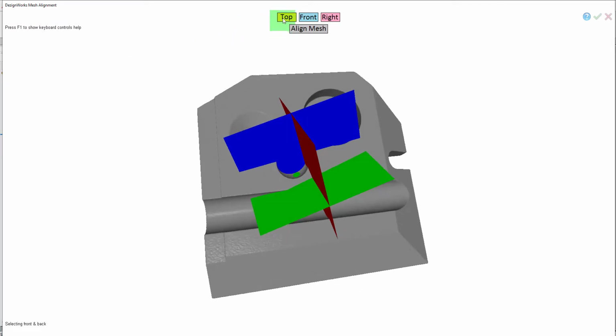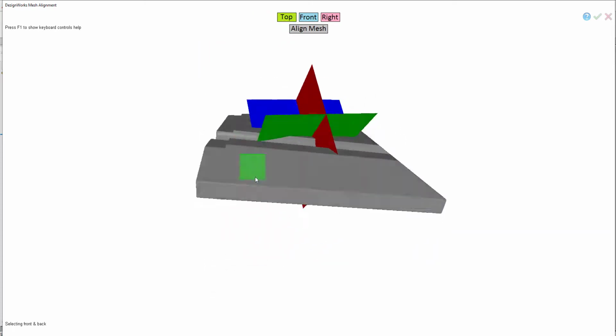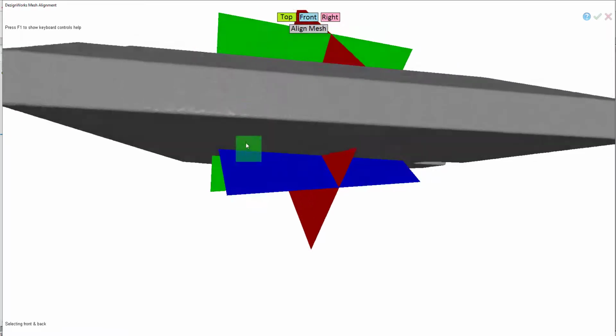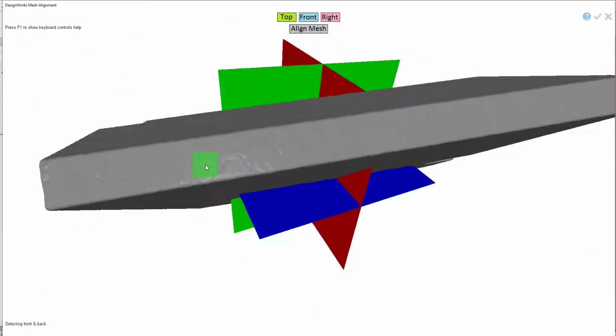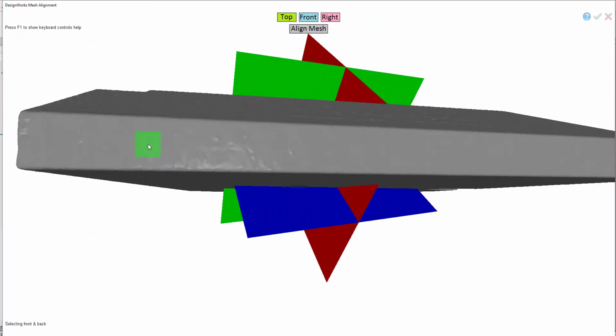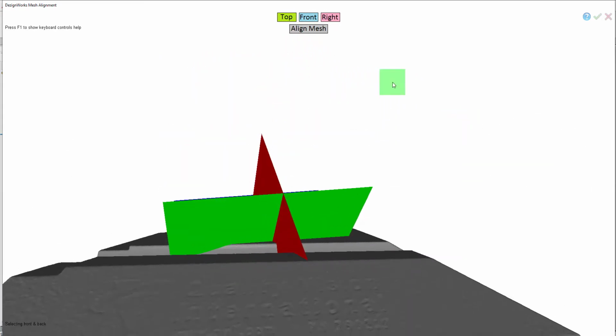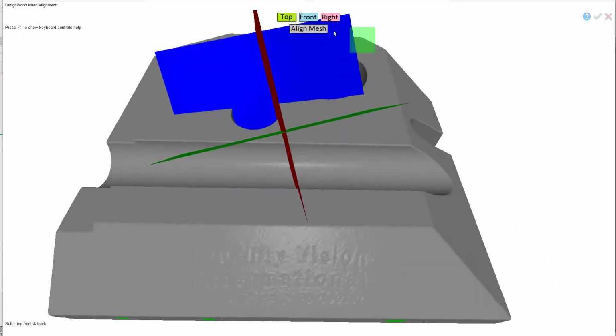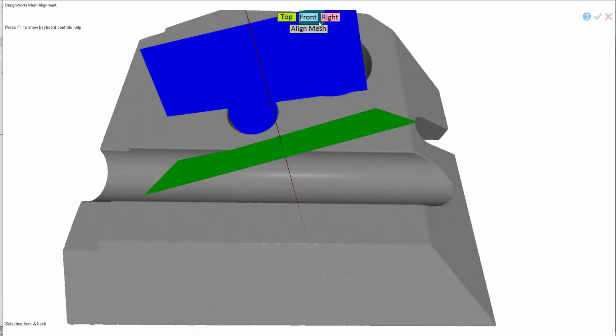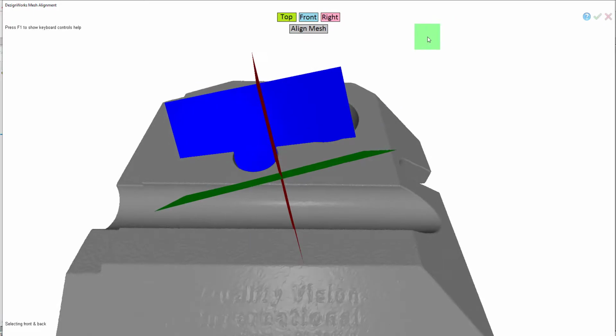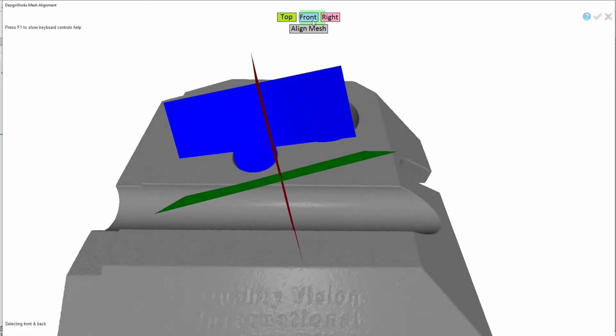Now that's in green, it correlates to the SolidWorks top, which would be across the front. So we're going to zoom in with the mouse, or if you have a 3D connection device, you can simply tap with the left mouse button and tell it this is the front. Come back up here. Make sure your part's not sitting over the icons, or you'll actually select on the part. So notice I moved the part from the icons. I'm going to say front.